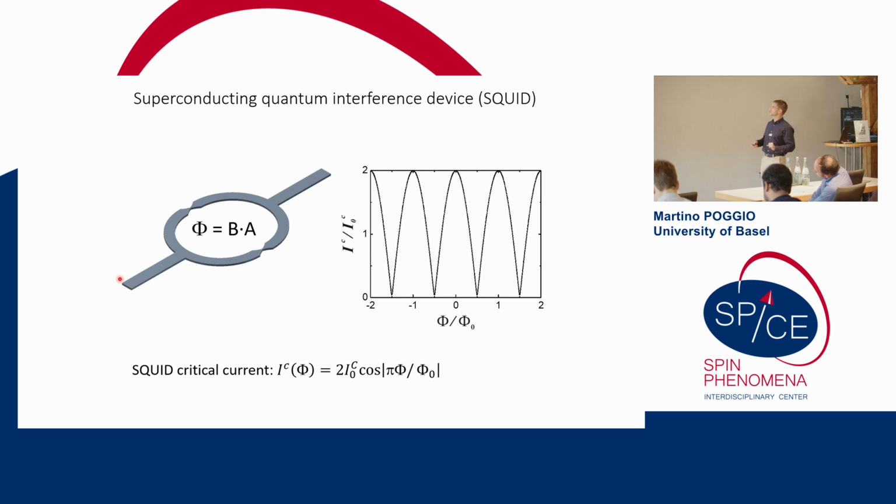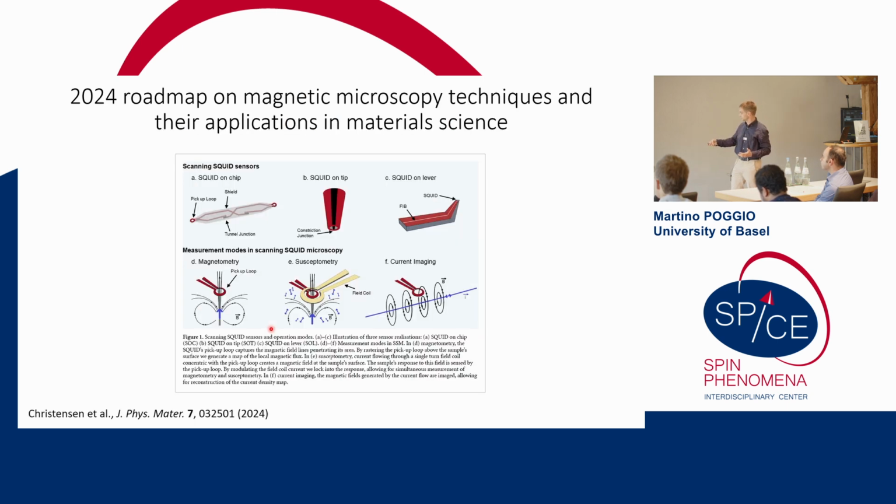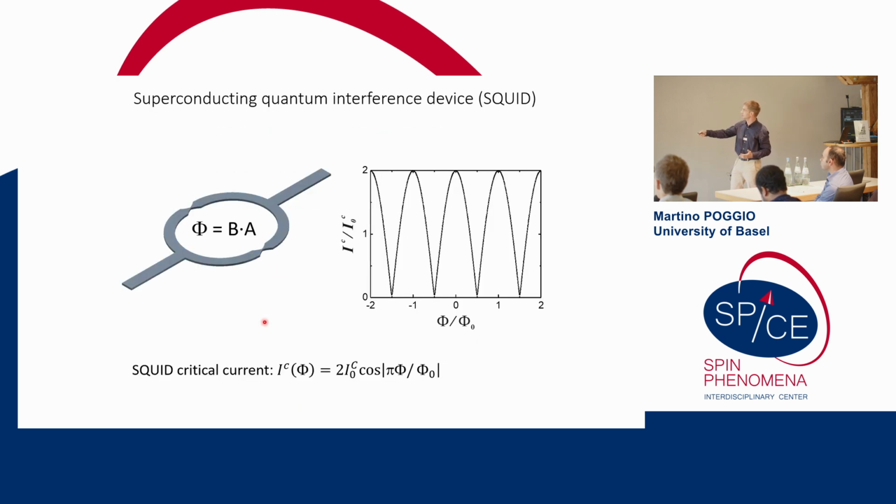Right, so I was talking about superconducting quantum interference devices. So they're excellent magnetic field sensors. They can also be excellent scanning probes, and this is not something new. This has been used for many, many years. And the basic idea is you make a squid, and you essentially make a measurement, and you move it to the next place, and you make another measurement, and so on. And so by the fact that you're making measurements of magnetic flux with a device of fixed area, you can then extract the magnetic field profile in so doing.